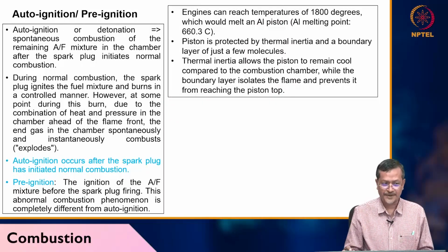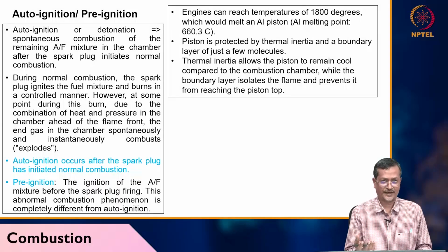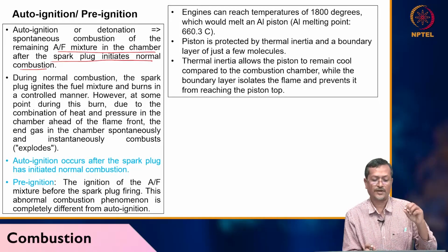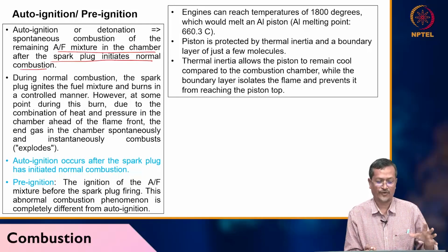Auto ignition and pre-ignition. Auto ignition is actually called knocking. Auto ignition, or detonation, or knocking, is the same term. It is the spontaneous combustion of the remaining air-fuel mixture in the chamber after the spark plug initiated normal combustion. The spark plug initiated it, but the mixture ignites quickly, so that creates a bang noise.